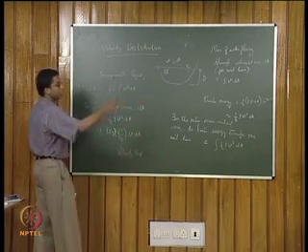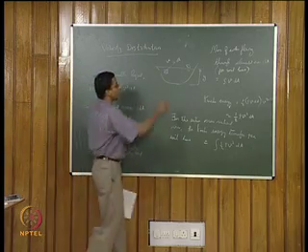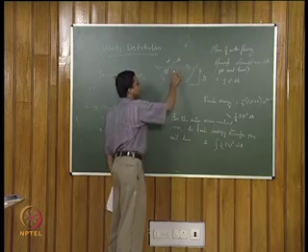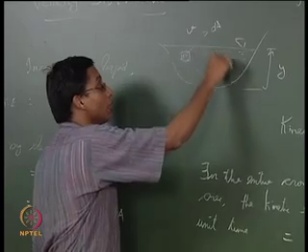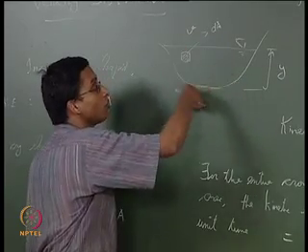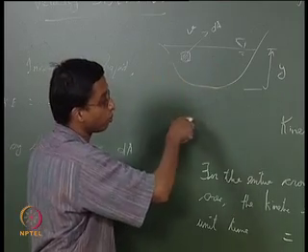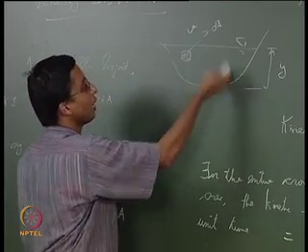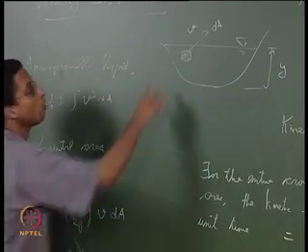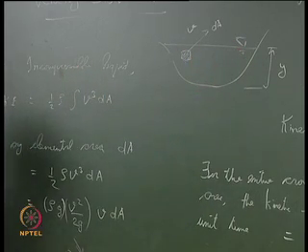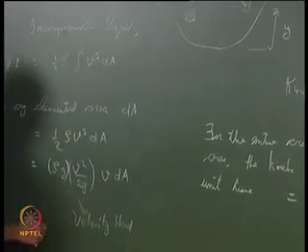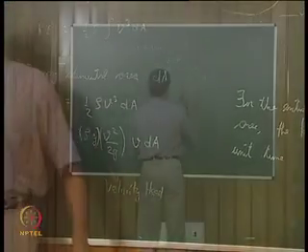You have already seen that the velocity head obtained by averaging all the velocities and subsequently obtaining the corresponding head, and the average of all the velocity heads from the cross section, are not the same. It has to be corrected by some factor, that now we are going to see.